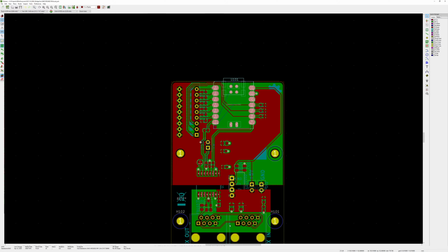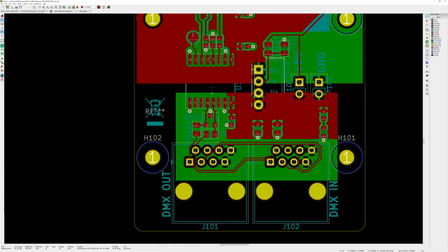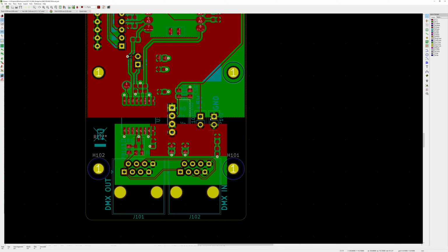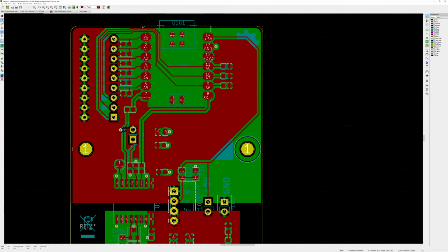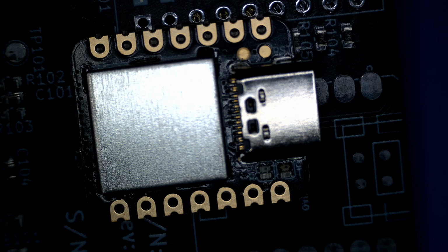That's why most footprints, like when you look at the SOT23, the centroid of the part is the center of the footprint. Same for all these passives. Center is center. Same for this IC. The center is the center. And you've got to be mindful of that when you are building your footprints. It's like start to finish, every little detail matters. And that difference is, when I flip back, that's the difference right there.